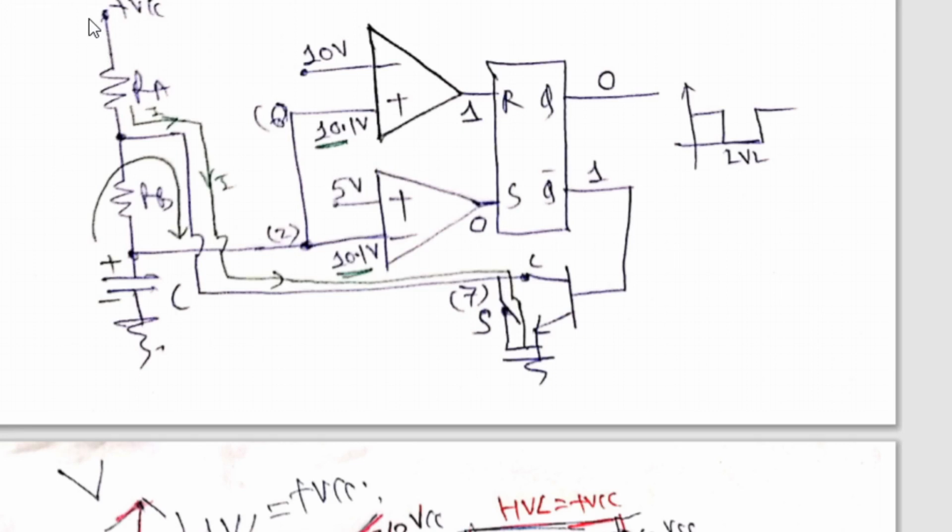The entire total current I, which was going to charge the capacitor, now that current will go through Ra, and then the current will get a least resistant path, that is the short circuit path. So the power supply's current will go through Ra, and it will go through the short circuit path of the closed switch like this. This is number one.